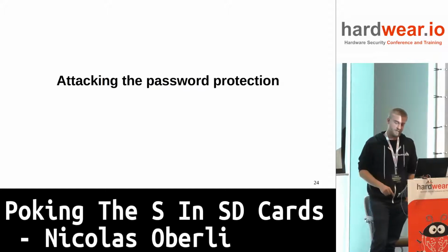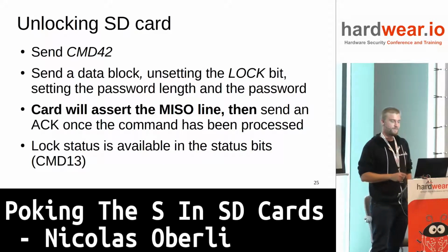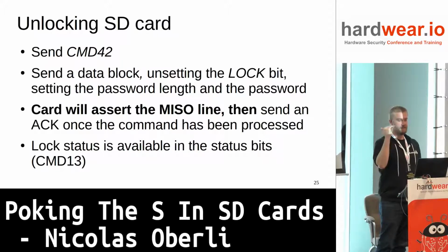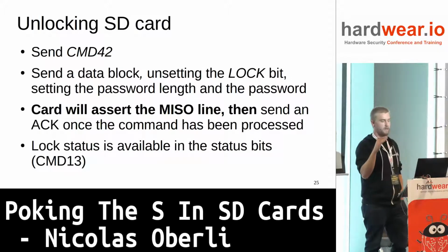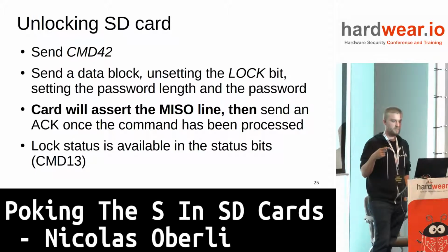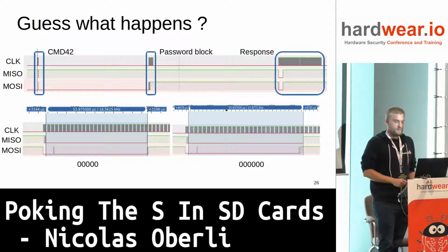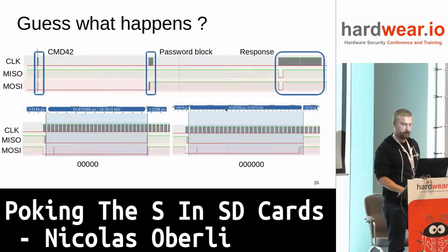So now the juicy part. As I said, the card will pull down the data line while it's processing the password, so no other commands can be sent during the password check. So what happens if I show you here? You can see this is a logic analyzer output. Basically you can see the status of the clock line, of the line from the card to the Hydra bus, and from the Hydra bus to the card.